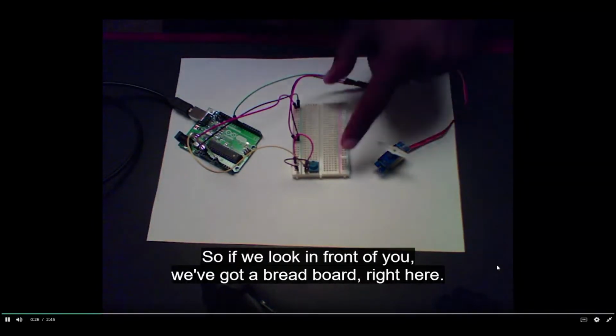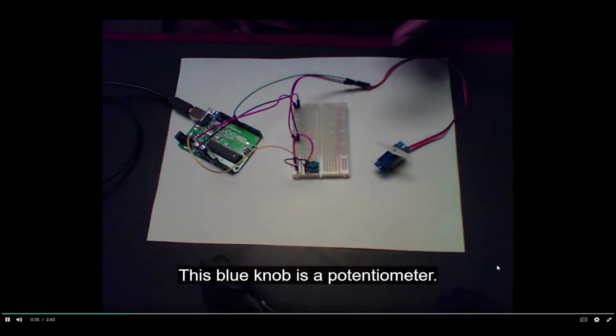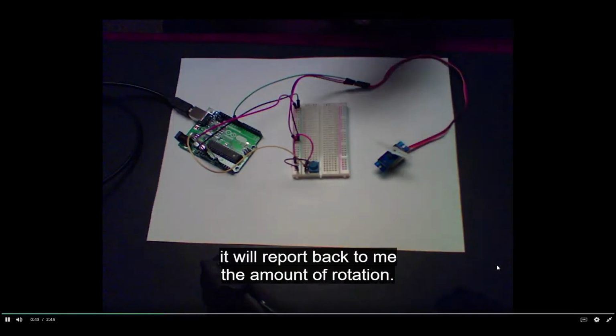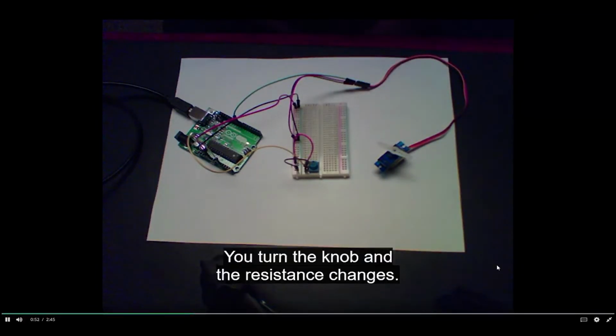So if you look in front of you, we've got a breadboard right here. And on this breadboard, we've got our sensor. This is a blue knob right here. This blue knob is a potentiometer. What it does is it senses rotation. So it's a knob. I can turn the knob, and it will report back to me the amount of rotation. It does that in terms of resistance. So it's really a changing resistor, a variable resistor. You turn the knob, and the resistance changes.